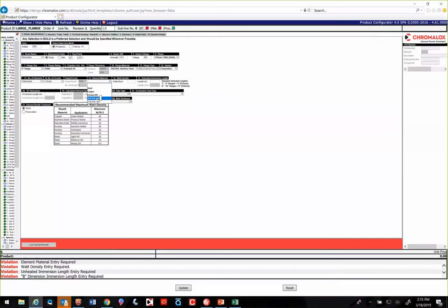From there you've got your element material, and that's based on corrosion guides, and if it's straightforward, that's easy. Now this is where it gets a little interesting. You've got standard cold ends that you put on things, and the standard is 4 and 6 inches. That's not that long. If you've got a regular 10-foot, 20-foot bolted tank, I'll put money the nozzle is going to be 15, 24 inches extended off the tank. You really don't want to put the heated section in there. So again, these are the standard. You can put longer cold ends. You can put 24-inch cold ends.